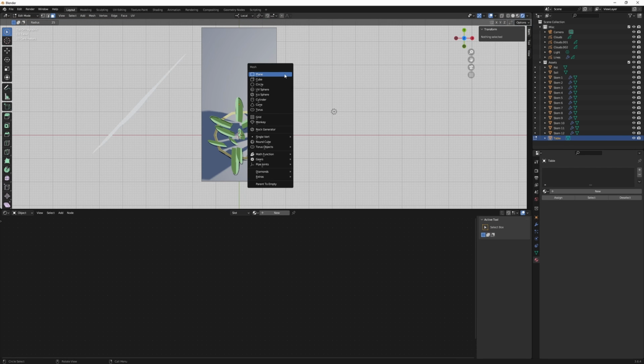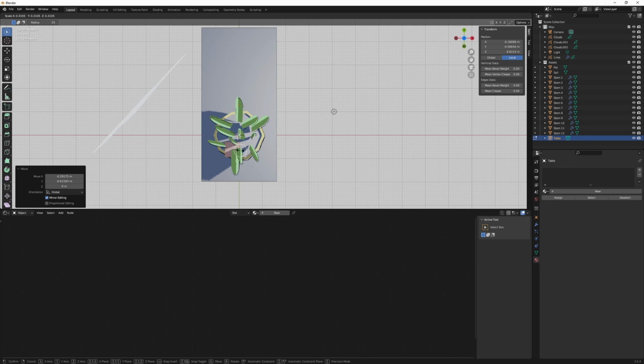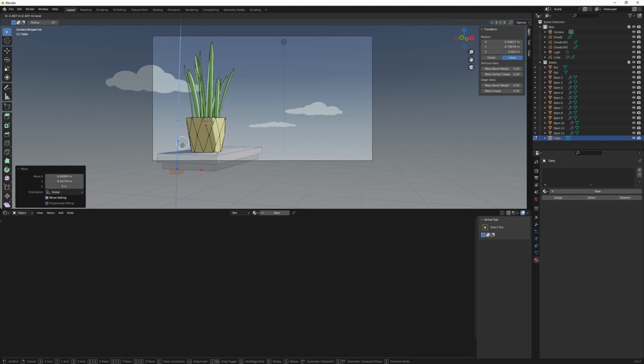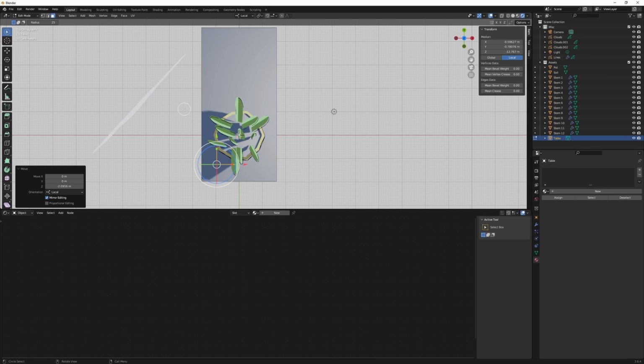Okay, now I'm going to top mode. I'll hit Shift A again, bring in a cube, grab that and bring it over here for a leg. Hit S to scale that, G to grab it, bring it over. Go to camera view, bring that down. Now hit S and Z to scale in the Z axis. Now bring that down. 7 on my numpad.